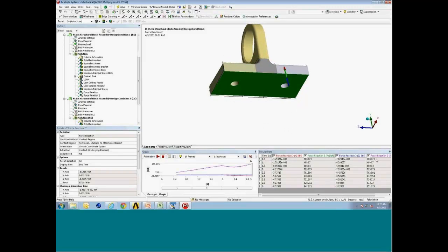Sometimes that's helpful. In this case, we can see with load step 1, I have 400 pounds pretensioning one bolt, and I have another 400 pounds pretensioning at load step 2. So here you can see the resultant pretension coming through this contact pair, and then as we load the bearing, you can see the various loads transferring through this contact pair.